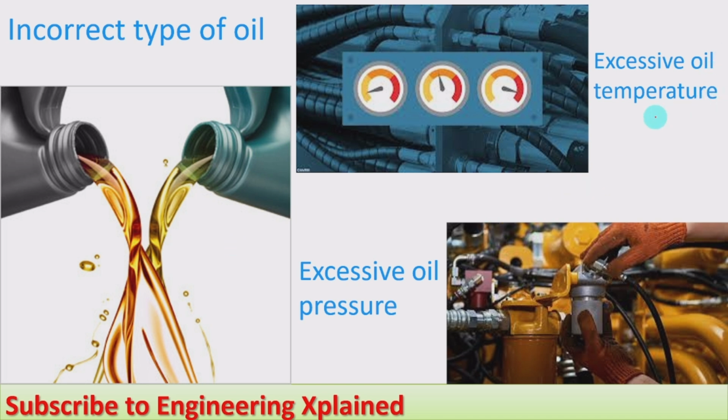The excessive oil temperature is next one. Excessive oil temperature means if we carry out continuous operation of the system, during that time the pressurized fluid, as it is pressurized, as it is an incompressible fluid, the liquid fluid is an incompressible fluid, and due to that during the pressurizing it will get heated and its temperature will increase. And if the temperature is maintained within the limit in the system, that will not cause any effect to the system.